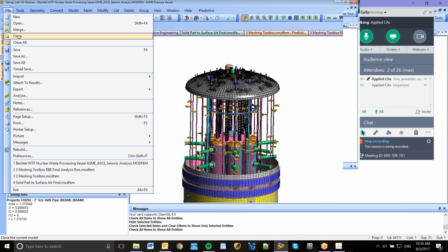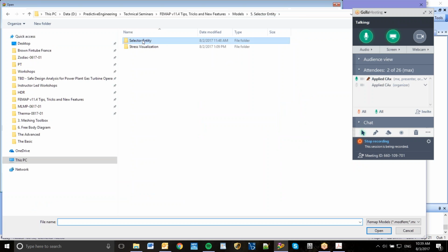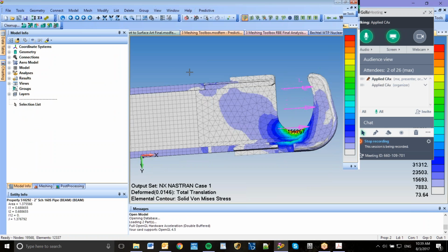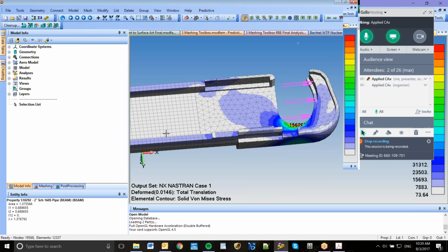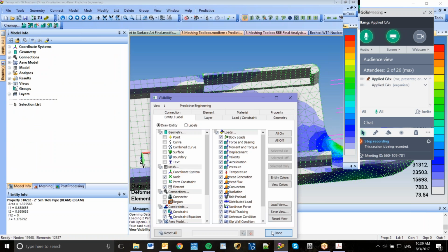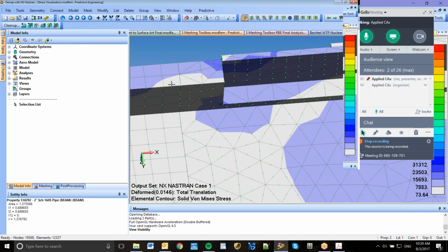And the next model, stress visualization. It's another thing we use the selector for. And when I mentioned this is my push for hex, what is hexable, and tet, the rest. The reason is that an 8-node brick is numerically very efficient. It's quasi-parabolic, isoparametric. To get the same behavior, you use a 10-node tet. To fill one cube, let's turn that element on, you have to use 5 tets, which has 26 nodes, where an 8-node brick is just 8 nodes. So the efficiency is more than 3x.